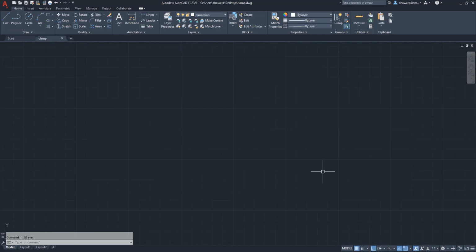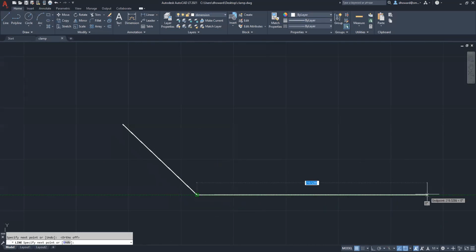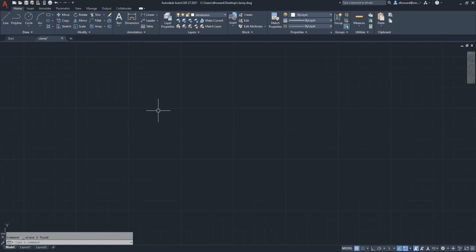I'm not going to try to do the foreshortened views or the auxiliary views before I do the view that is true size. And I am going to draw it basically in this layout, going like that. So that's the general shape that I'm going to draw this thing in first. Kind of opposite, I'm rotating it around, and that's just so I don't have to do as many hidden lines.